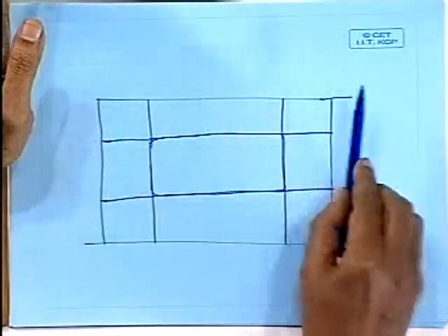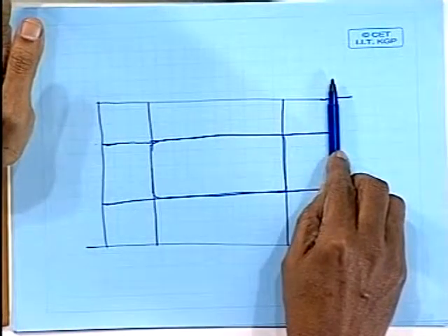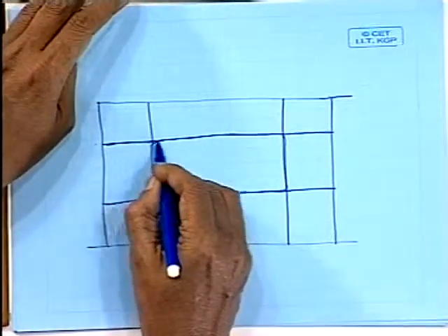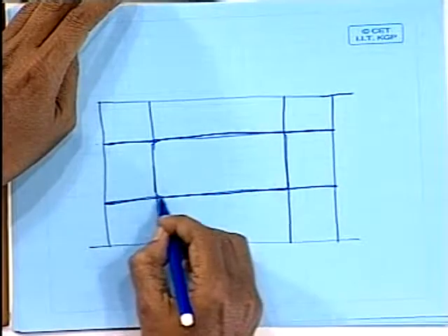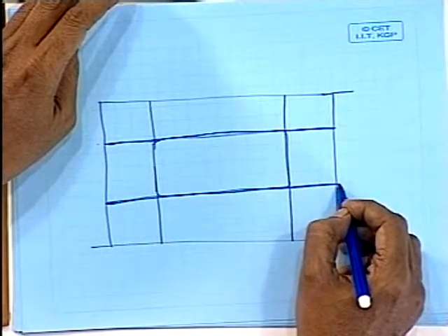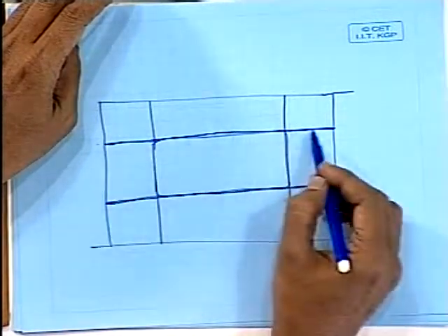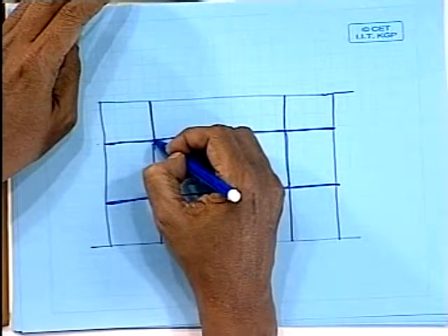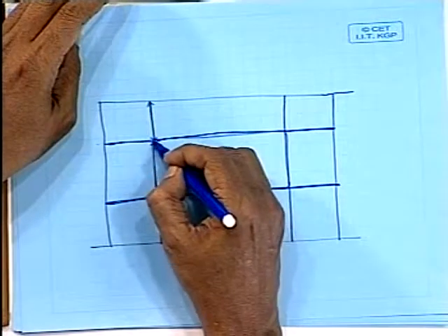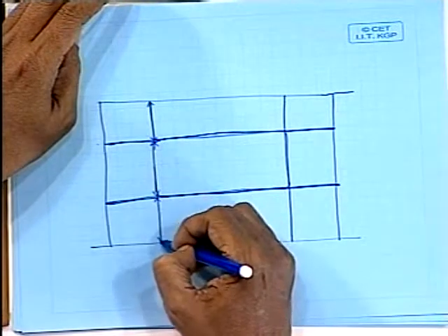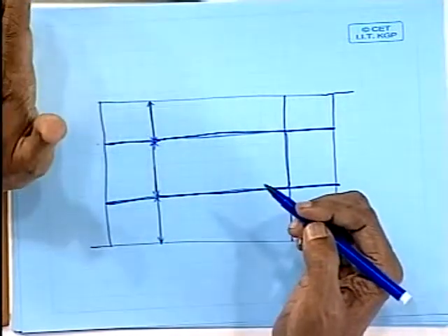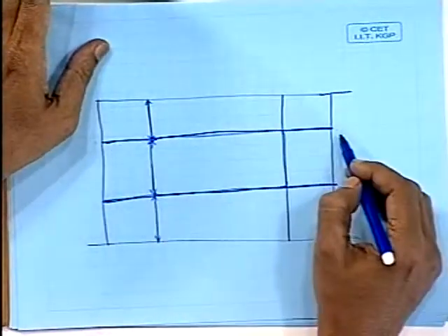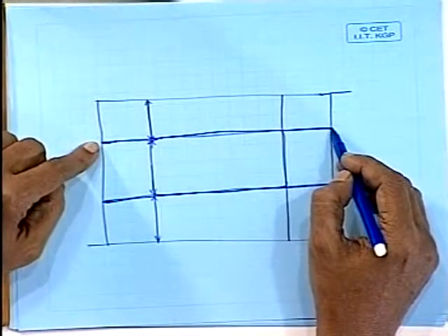Now, which are the primary members? How do you design these girders and beams? If you take the bulkheads as your primary support, then the girder is designed first, and that girder breaks the span for the hatch end beam. That means the hatch end beam becomes smaller. This part is designed with this span, this part with this span, and this part with this span. But the girder is very big because, as you can see, the span is large.